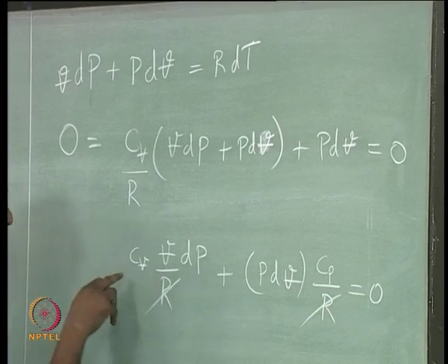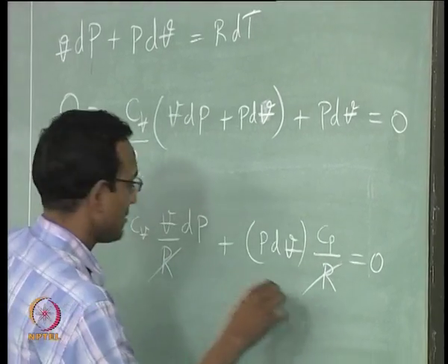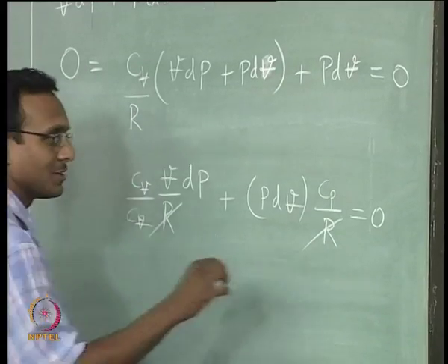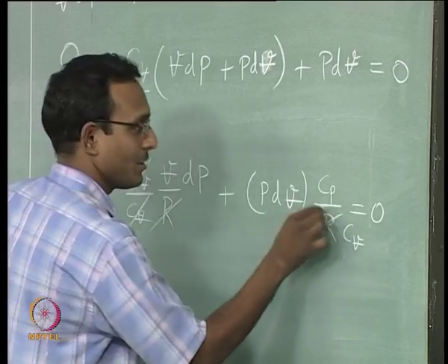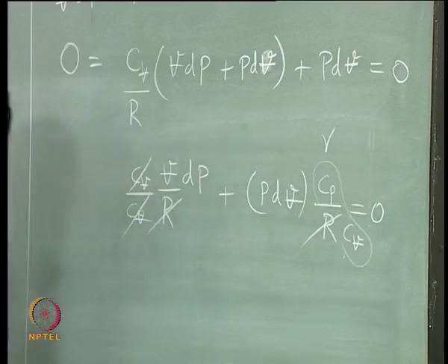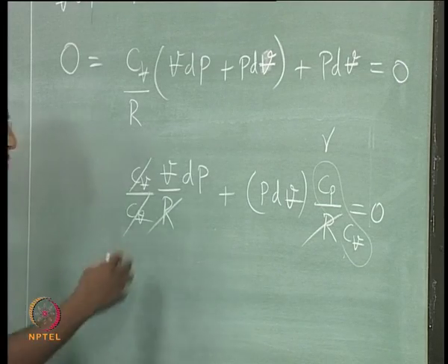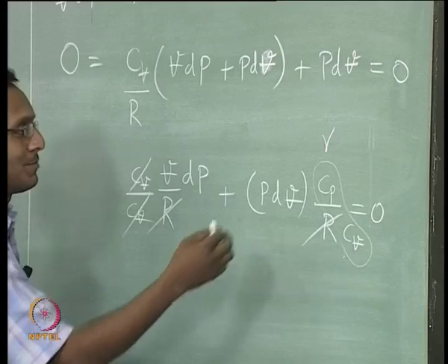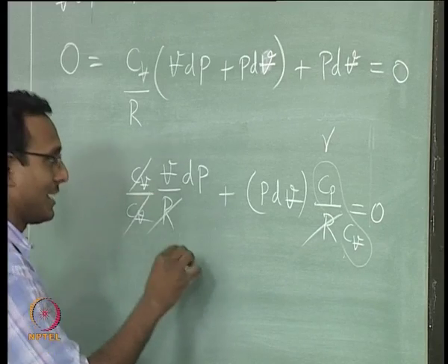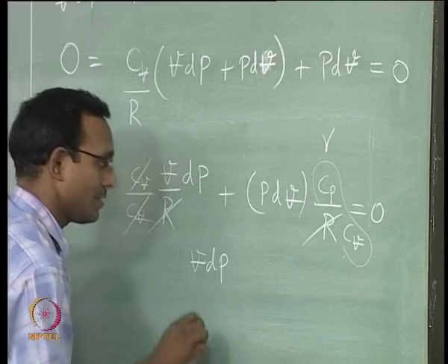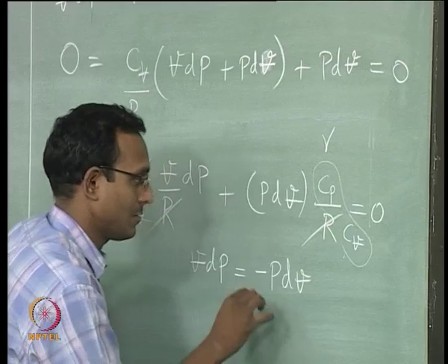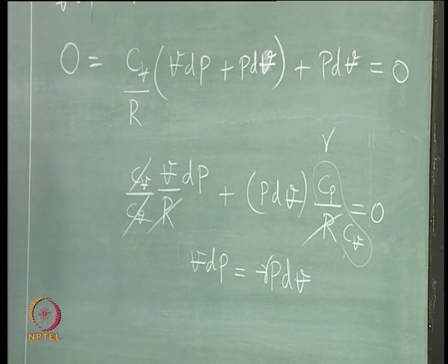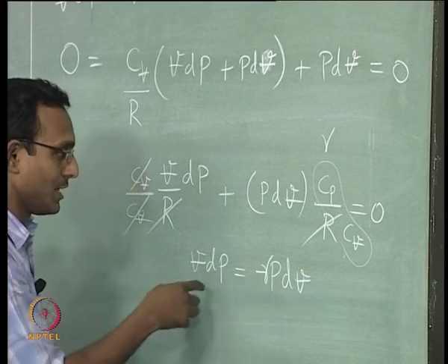I will rewrite this a little bit. I will take this Cv, divide by this. So, I will get divide by Cv on both terms. This will become your gamma. So, I can write a simpler expression, take one term to the other side. So, let us say I will keep V dP minus gamma P dV, get to this form. Now, I will just put dP by P.